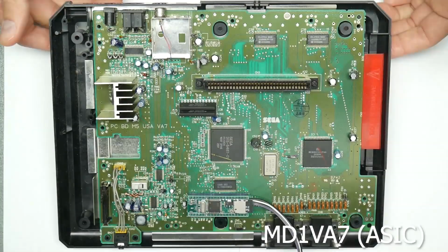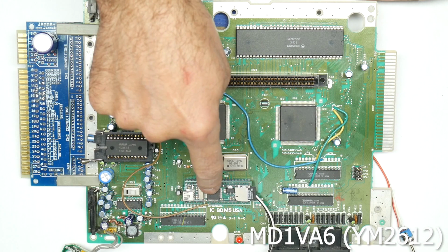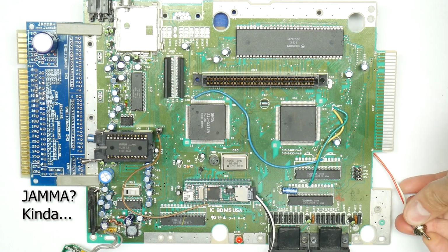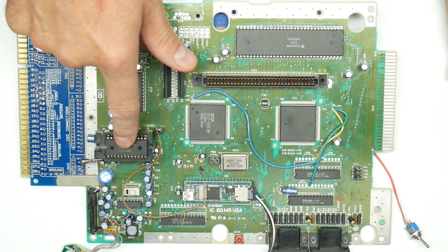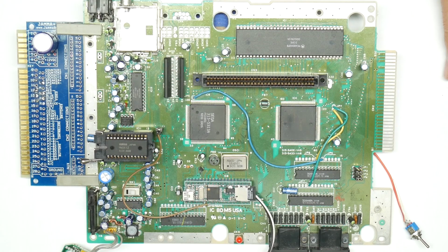The third setup uses a modified Mega Drive PCB. The Z80 is replaced by my very own ICE80 board. The PCB is permanently stuck in Sega Master System backwards compatibility mode by a switch, and since the Z80 has no known way to toggle the YM2612's chip select pin in SMS mode, I kind of hacked the cable from the one unused pin of the ICE80 board directly to it.